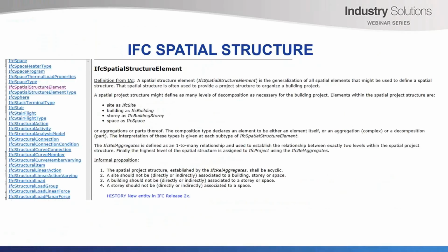Spatial structure. Now this is an interesting one, and you can see why IFCs really have come from the building world, because you can give things multiple spatial structures. You have a structure, you can have an IFC site, and then inside you have an IFC building, and then you can have an IFC building story, and then an IFC space inside that. So everything's supposed to be given this spatial structure. So yep, it's all very good, but I'm not certain if too many of our road projects fit into being called a building or a story or an IFC space. So yes, they could fit in an IFC site, but the rest of the spatial structure for civil at the moment is a little bit vague and really does not exist there.